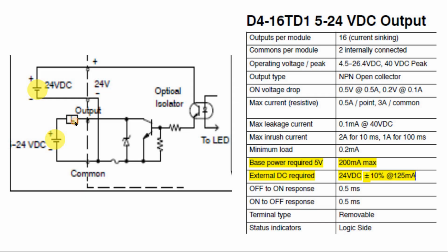But does your load really require 0.5 amps or less or more? It's up to you. Now, if you have a relay and this relay coil requires 0.05 amps, you can forget about this, and you say my usage is so and so. That's a lot less than what's in here, but this will give you the maximum you can draw from this card.